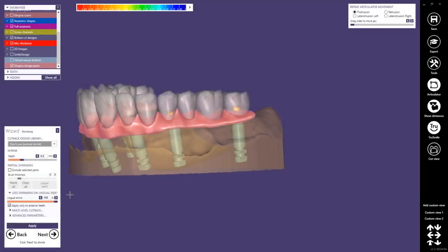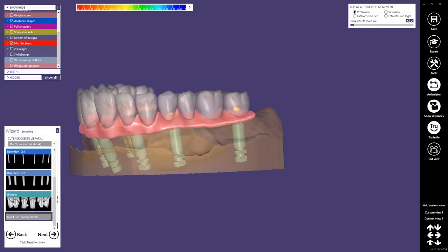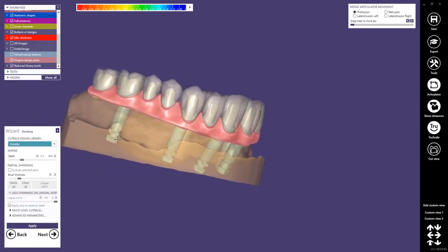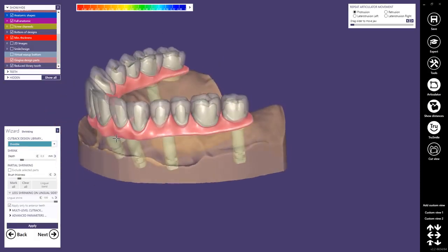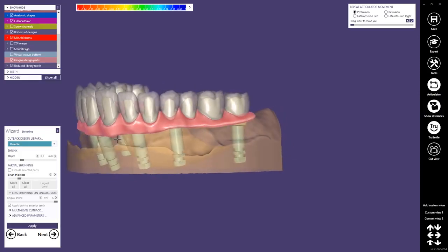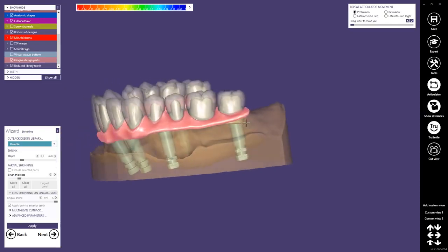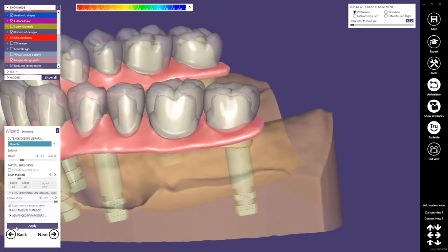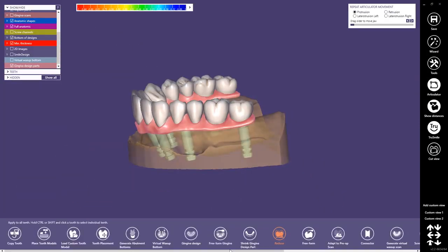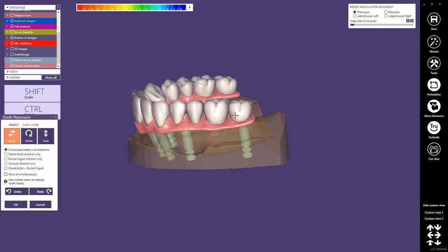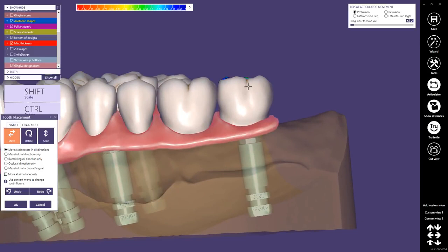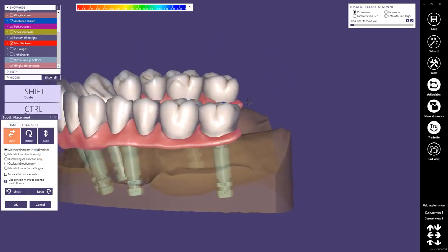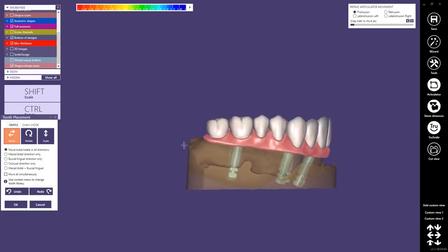Yeah, in this step we can now create the thimbles by choosing the thimble cutback library, and automatically the anatomical teeth will be adjusted, or will be shrunk, in a way that they look like a thimble. Yeah, here we would obviously have maybe a problem with our margin area. No problem. We can go to the expert mode and still do a change here in the tooth placement, and create more space here or make a shorter thimble. And we could also go back again and recompute the gingiva if really required.